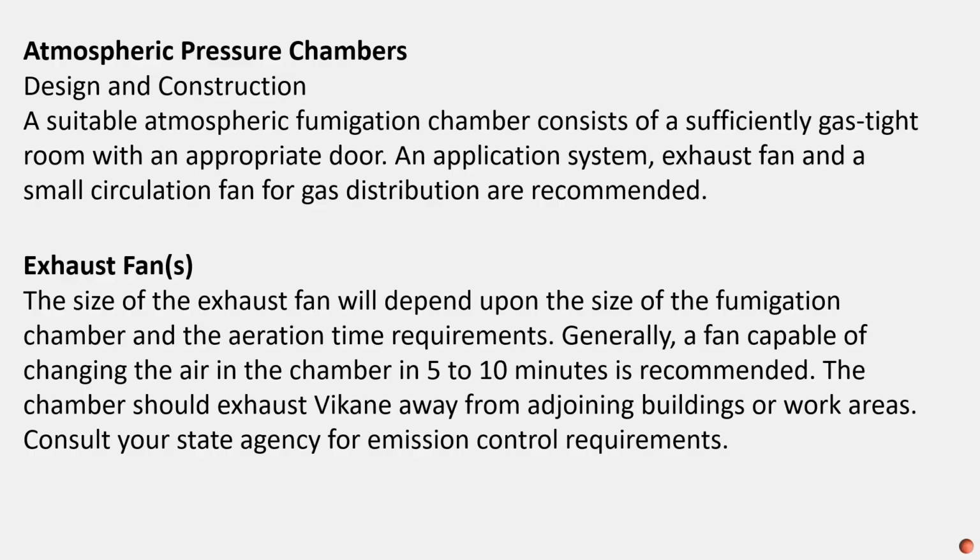Atmospheric pressure chambers, design and construction. A suitable atmospheric fumigation chamber consists of a sufficiently gas-tight room with an appropriate door. An application system, exhaust fan, and a small circulation fan for gas distribution are recommended. Exhaust fans. The size of the exhaust fan will depend upon the size of the fumigation chamber and the aeration time requirements. Generally, a fan capable of changing the air in the chamber in 5 to 10 minutes is recommended. The chamber should exhaust Vikane away from adjoining buildings or work areas. Consult your state agency for emission control requirements.